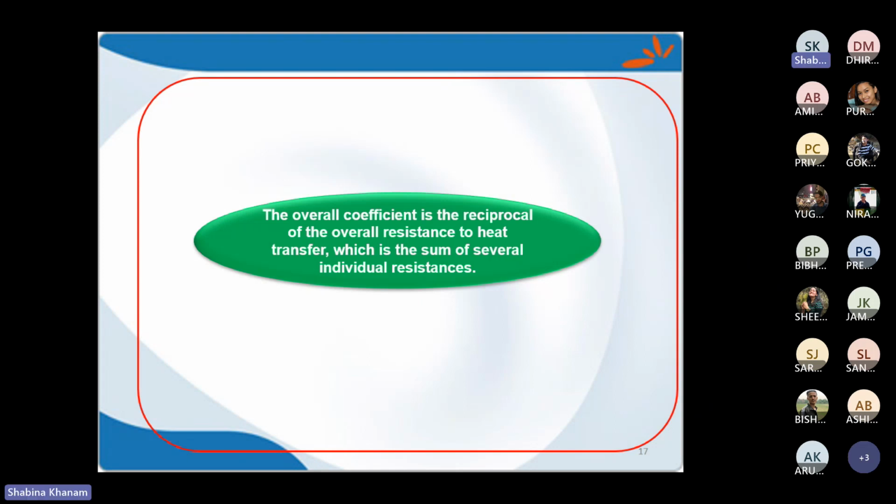So, when we consider a shell and tube heat exchanger, if I consider a single tube, on the shell side we have a fluid, and inside the tube we have another fluid. So how many resistances will there be? For each fluid there are three zones: one zone is the shell side fluid, another zone is the tube side fluid, and the third zone is the wall, right?